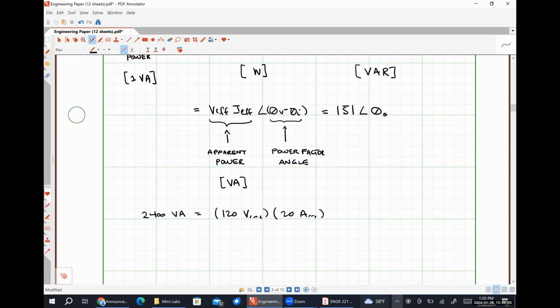If the voltage is a fixed value, like it is here in the United States for any receptacle, where it's going to be either 120 volts for a standard household receptacle, 240 volts for a receptacle that's used for like your oven, your dryer, and things like that, you can easily figure out what currents you can handle just by looking at the apparent power rating of your load and then say, this is what wire I need for this thing.